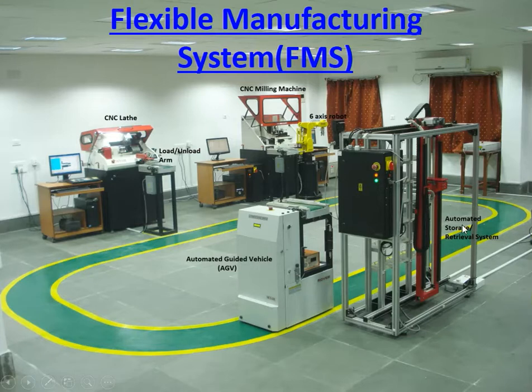And here you can see this is the automated storage and retrieval system, where the material required will be stored over here, and it can be retrieved also once the machining process is done from this particular AGV. So the AGV is the one which is traveling through the loop, and this is a flexible manufacturing system where different operations can be carried out in one single setup, in a system or a machine cell.